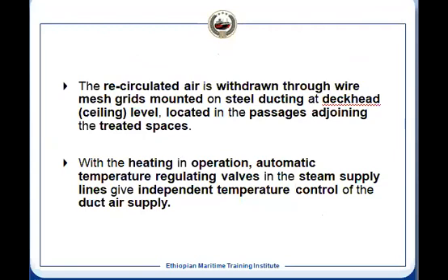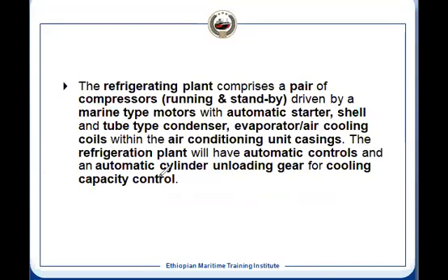So then we have the other components, like the compressor. There will be two compressors. One will be in running condition, another will be in standby condition. And this type of compressor, we have different types. We can have the reciprocating type, and V type, which will have the higher capacity, and you can have a screw type compressor also. Both are in use in air conditioning plant.